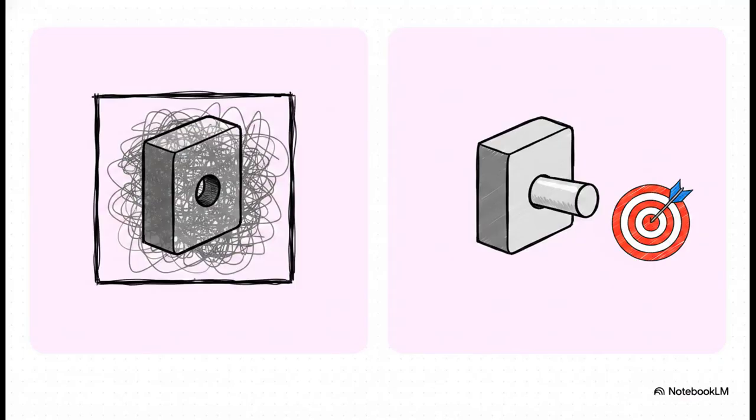Think about the fundamental contrast between traditional plus or minus coordinate tolerancing and GD&T position tolerancing. With coordinate dimensions, you are relying on rigid, square boundaries. If you're designing something like engine mounting holes, this naturally leads to tolerance stacking. The center points drift out to the extreme corners of those theoretical squares, pushing the physical holes entirely out of alignment. That accumulation of error is exactly why parts fail to assemble, even when the numbers look totally fine on paper. Position tolerancing, on the other hand, replaces those restrictive squares with boundaries that actually make sense for circular fasteners. It gives you functional location control that actually guarantees a fit.